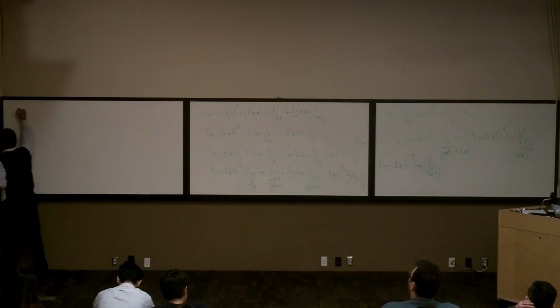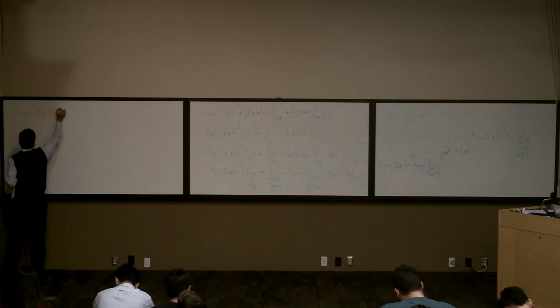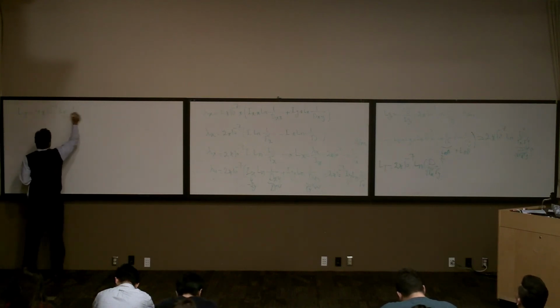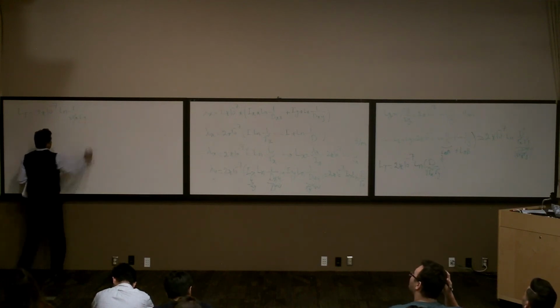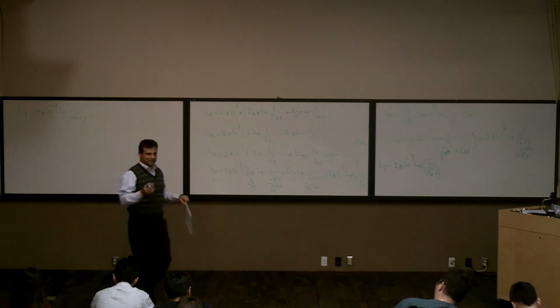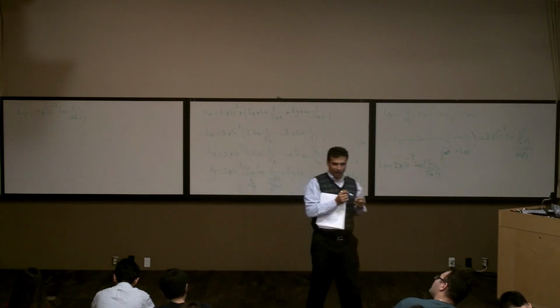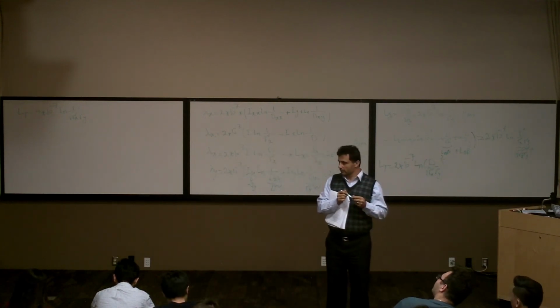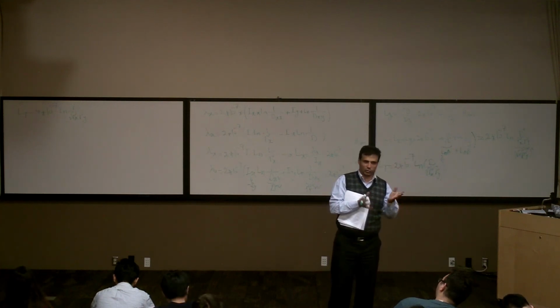So L total is going to be 4 times 10 to the power of minus 7 ln of d over the square root of r prime x, r prime y, right? But usually, when we have a single phase system, you have a 2-wire system. Rx and Ry are equal, right? They are not different. One of them is not smaller, one of them is not bigger. They are usually the same.